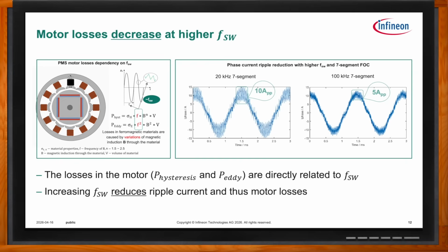And when I reduce my ripple current, so when I go up in frequency, my delta I, the ripple current, goes down. And it goes down to the N power here, as you can see, compared to linearly with frequency. So the eddy current kind of balances out. The hysteresis losses go down significantly as you go up in frequency, all other things being equal.